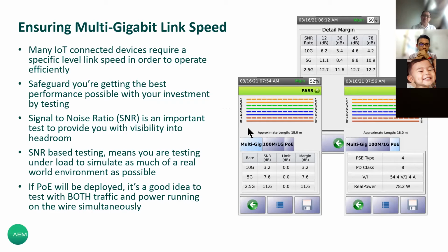Live operation means the other end of the cable is connected to a live switch. If your switch is connected at 1 gig or 10 gig at the outlet, we use our tester to measure the quality of the speed. And we measure it by the SNR parameter.